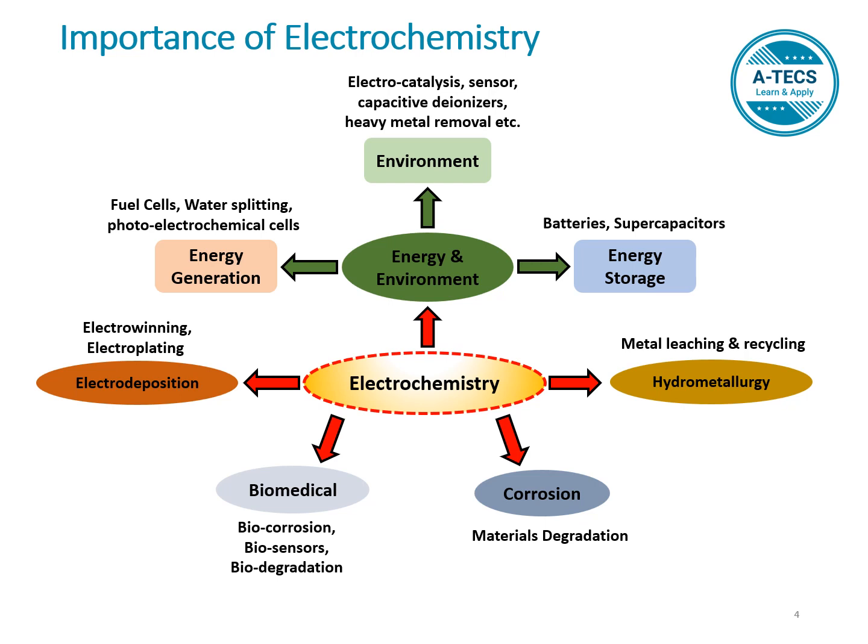For example, corrosion of steel is an oxidation of iron, and it is supported by the reduction of other species, for instance, dissolved oxygen in water and hydrogen ions. And during the process of corrosion, we have the progress of electrochemical reactions. And somehow we also have some chemical reactions during the corrosion process.